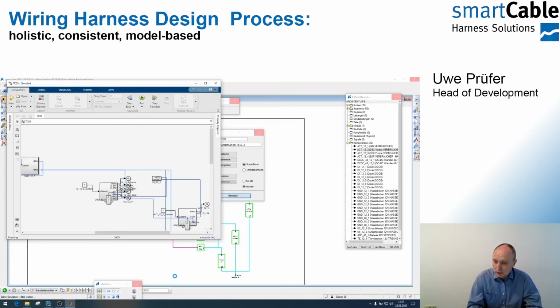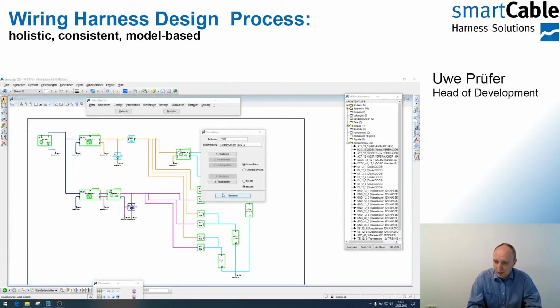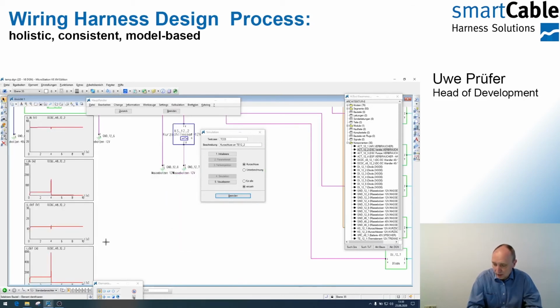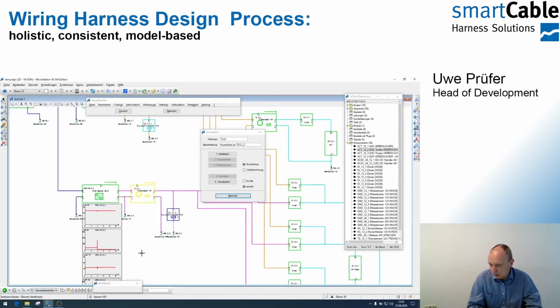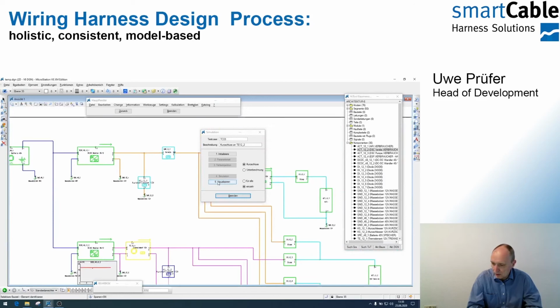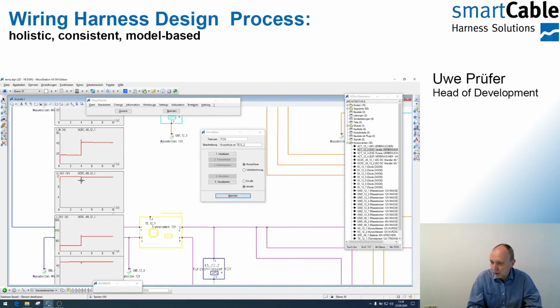simulation model. The simulation runs, and we transfer back the results from the simulation, and we can visualize it here. You see after 4 seconds the voltage and the current, and you see the peak from the short circuit. This is for the secondary net, and after it the secondary net is isolated, so every actor must use the primary net. You also see the peak here, and you see that the current is doubled after those 4 seconds.